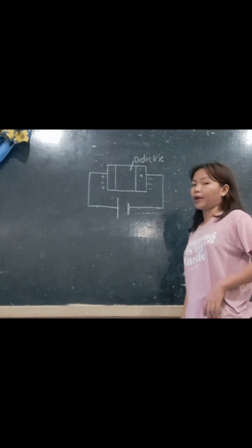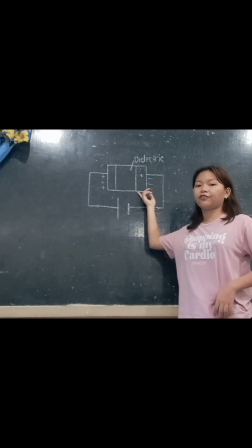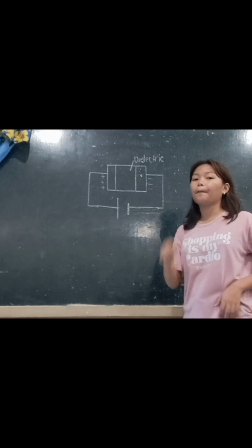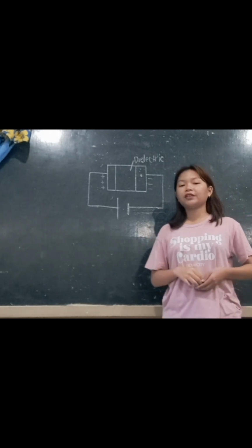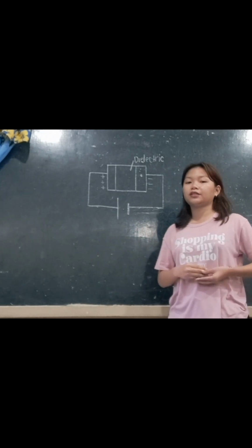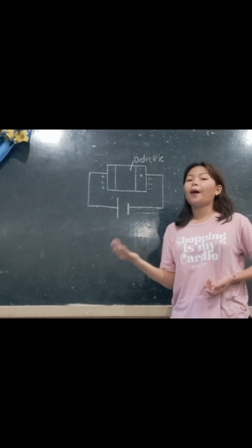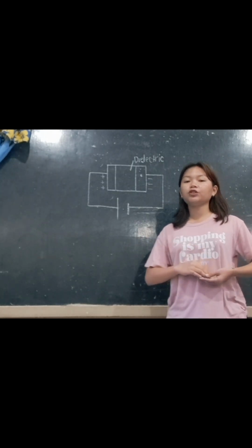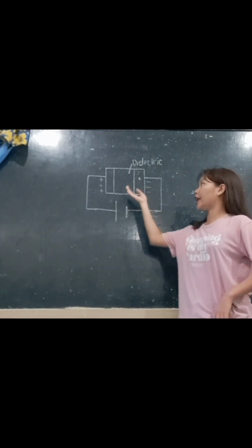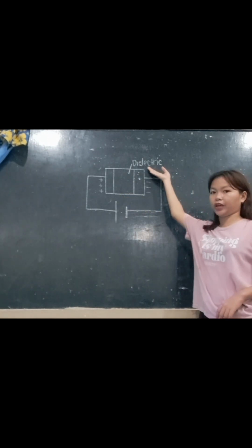In its basic form, a capacitor consists of two or more parallel conductive metal plates which are not connected or touching each other, but are electrically separated either by air or by some form of good insulating material such as waxed paper, mica, ceramic, plastic, or some form of liquid gel as used in electrolytic capacitors. The insulating layer between the plates is commonly called the dielectric.